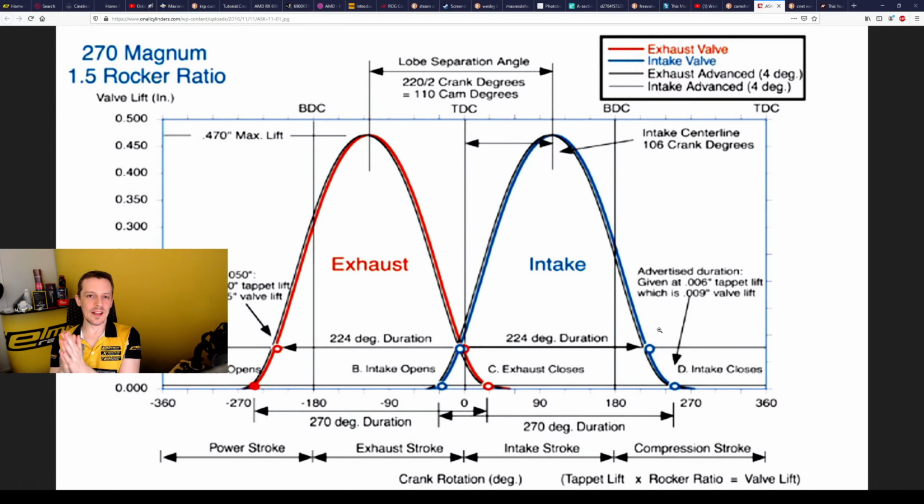Otherwise that means that in certain areas you don't really need to be pushing everything absolutely to the maximum. So yeah, it's cheaper, easier, more lightweight components also, so less wear and tear and all kinds of other components. With sodium filled or Inconel exhaust valves, for instance, the mass of the valve goes up, so that ends up wearing more on the components, reducing their longevity also.